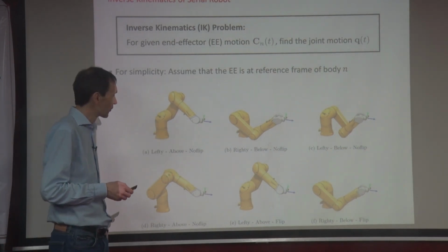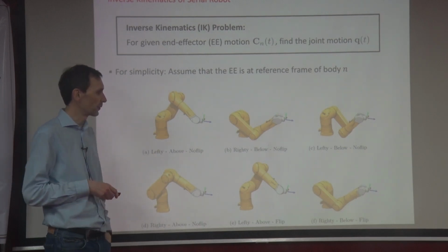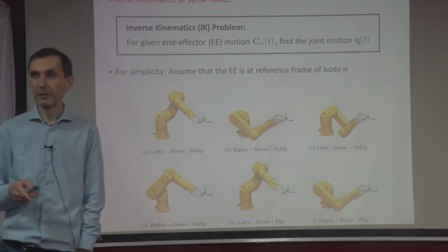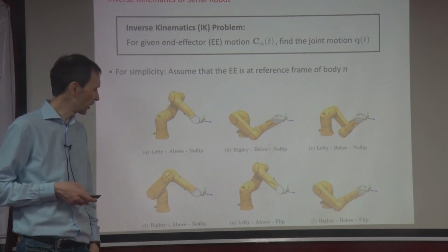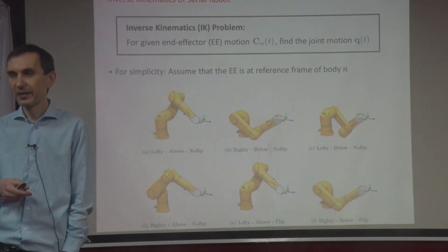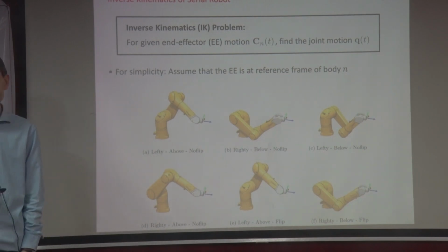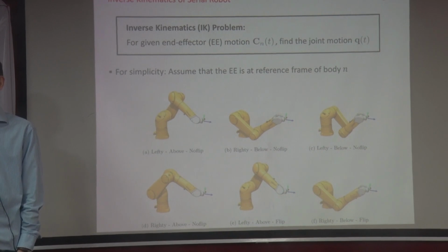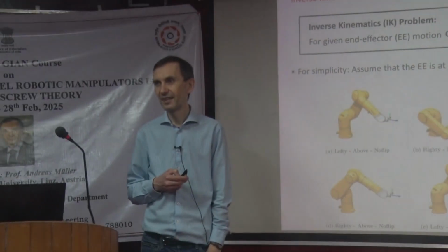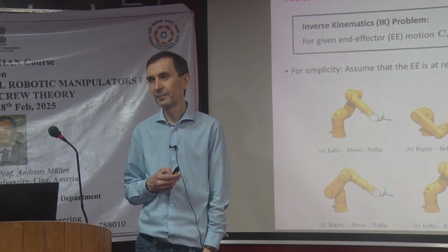Anyway, how do you solve it? How do you find these inverse kinematic solutions? There were two good answers: one said numerically and one said explicitly. Do you have an explicit closed form solution for this? There is actually one, but it takes a lot of time to even compute at the math level if the degrees of freedom or number of joints increases.